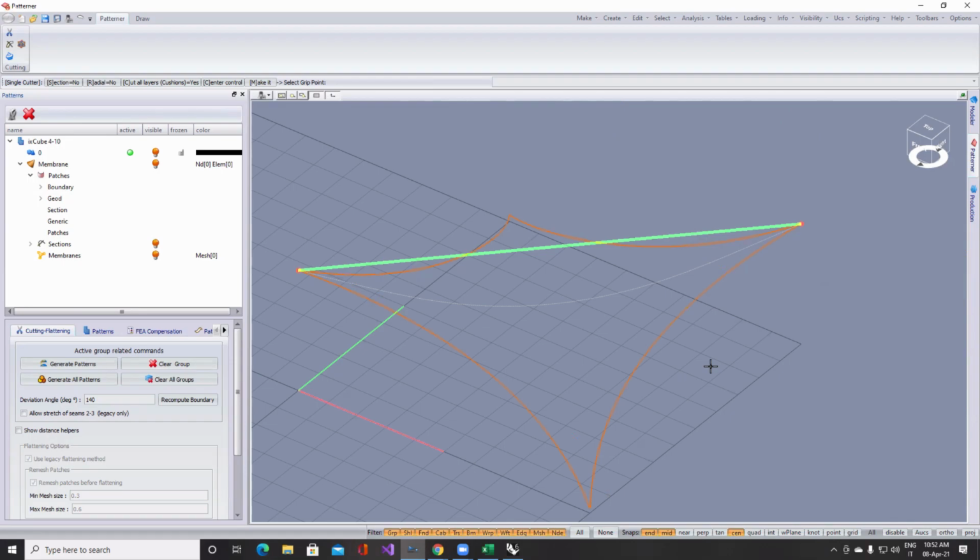And that means basically that when we flatten a part of the surface defined by geodesic curves on the ground, these tend to be straight edges. So you understand that when we want to produce flattened parts of surface, we want them to be as straight as possible because we have to cut these membranes out of a roll of membrane that has a fixed width.